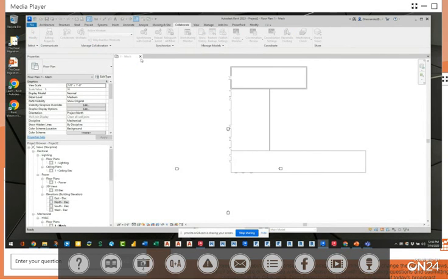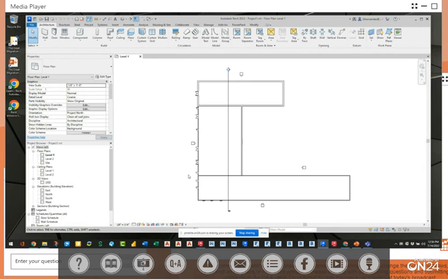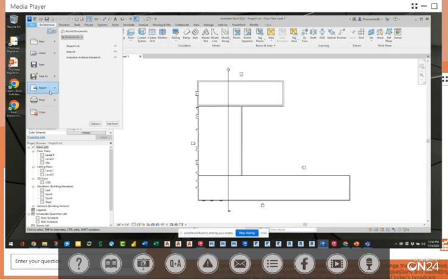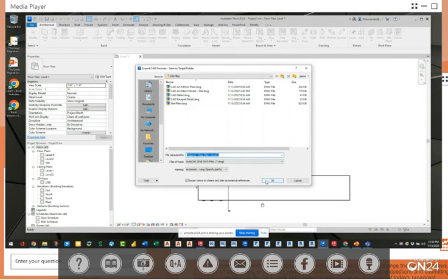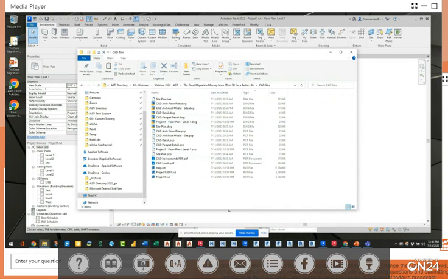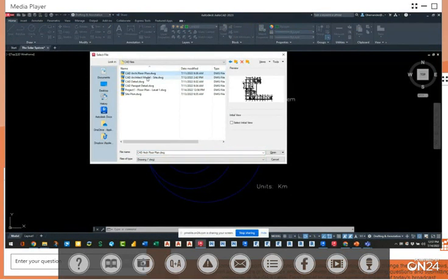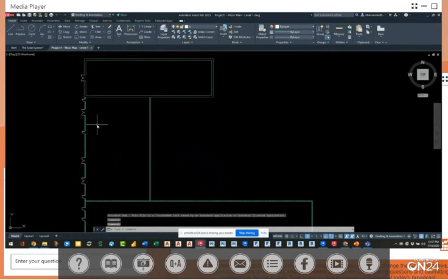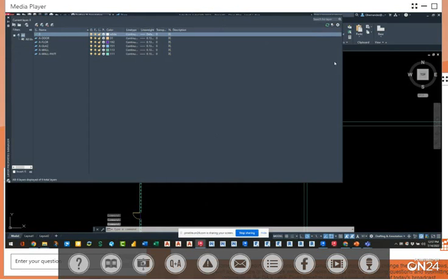Now, once you get into what you've developed in here, you could go backwards. You don't necessarily want to go back to AutoCAD, but what if I did? You could use these tools like export here to CAD formats. I can generate my own DWGs, my own CAD exports, and those CAD exports will look something like this here. They come with their own layer styles and everything already generated, kind of set up for you. So you can go back and forth using the AIA layer standard if that's your standard, right?